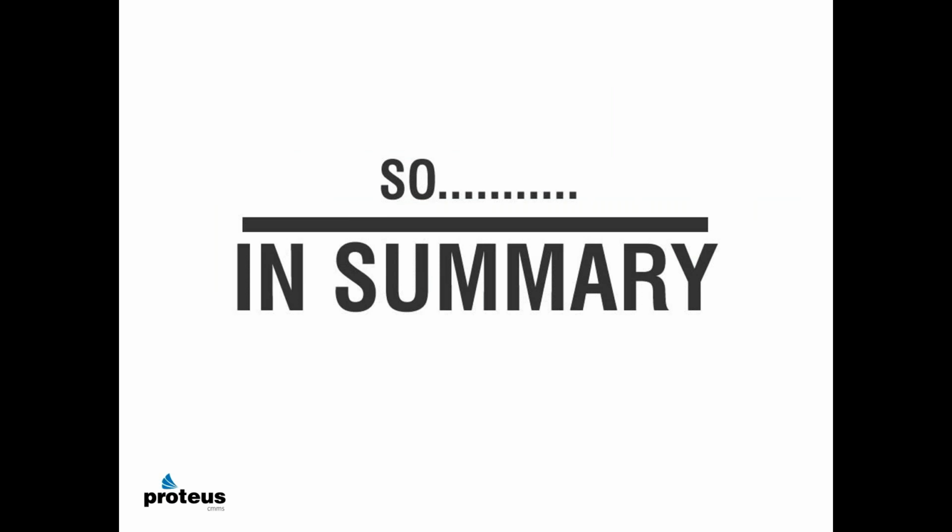So in summary, we can look at hours, we can look at mean time to repair, we can look at mean time between failure by machine, by plant, number of incidents where production is stopped by machine or by work type, by work orders by priority, and putting all of this information together in your particular case as a user of Proteus will give you a significant amount of information to manage with.